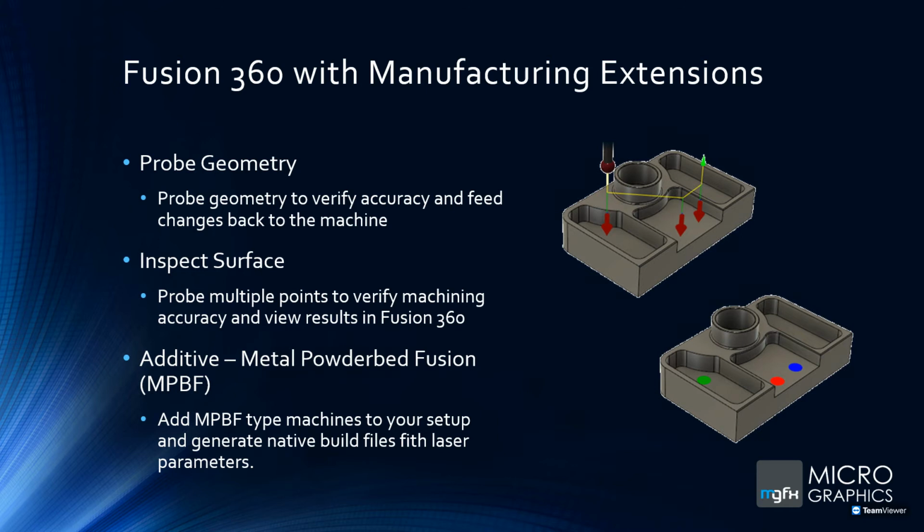That report that is pulled back is compared with the original model in CAD. That CAD and the real-life dimensions that are measured show comparison. You can see that the green dot there, that is within the specified tolerance. The red dot will be below tolerance, so you've machined away too much material. And the blue dot is above tolerance, which means there's still more material that needs to be machined away from the part. So you can do quality control while the part is still in the machine.